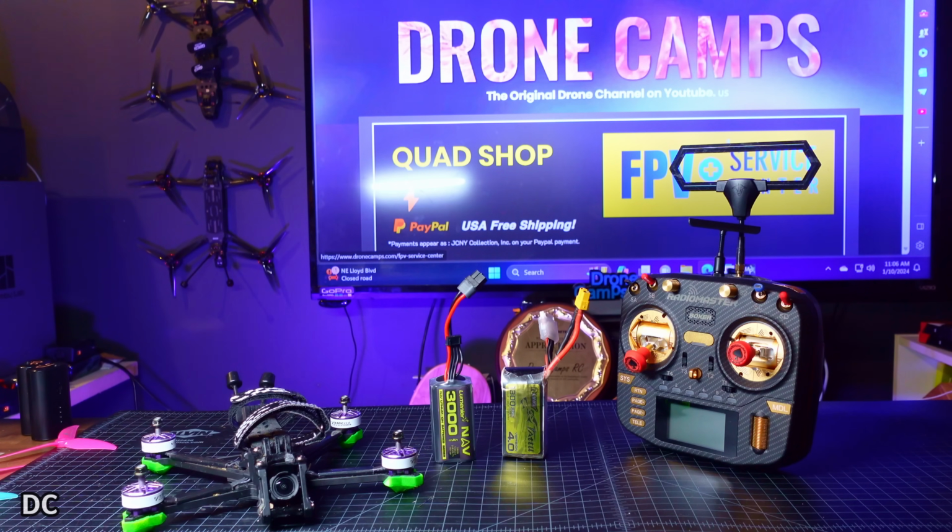So I have my 7-inch quads hanging back there on the wall. You can see them on the left. Those are my coveted 7 and 7.5 inch quads from Geprc, the Mark 7 and the Crocodile 7.5 V3. I love those quads. Both of those can fly on both of these types of batteries. You will fly mostly a 6S 8000 milliamp pack. That's about the average pack that you're going to fly on these big 7 and 7.5 inch quads, and 8-inch and 10-inch quads can also handle those types of packs. 8000 milliamps is a lot. It's going to get you up to about 30 minutes of flight time.